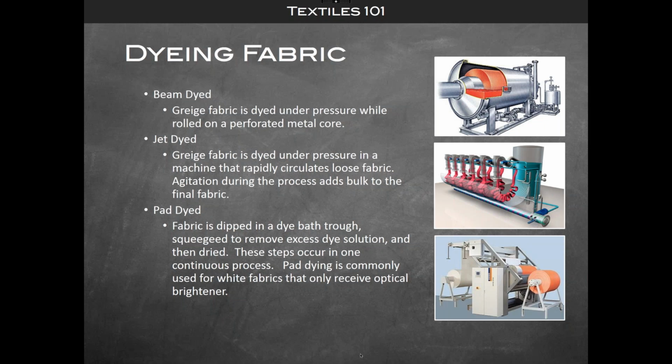The third method on here is pad dye. With pad dyeing, fabric is dipped into a solution and then it goes through a squeegee that will remove the excess chemistry. Pad dyeing is typically done in a continuous process. So this may be during the finishing process where you'd see pad dyeing. Pad dyeing is also commonly used for white fabrics that only receive optical brightener, as an example.